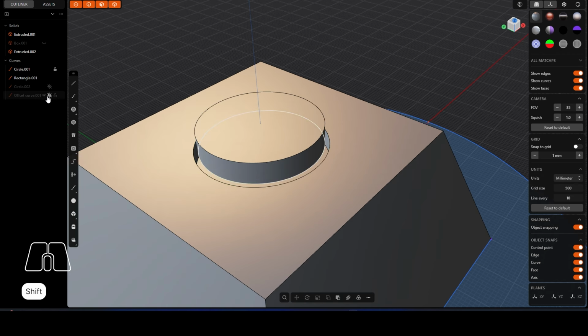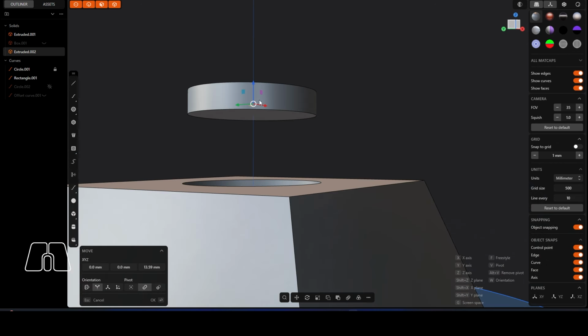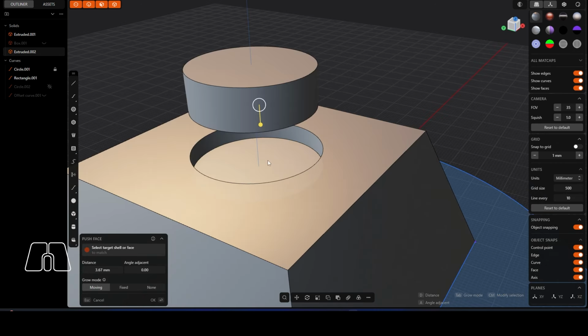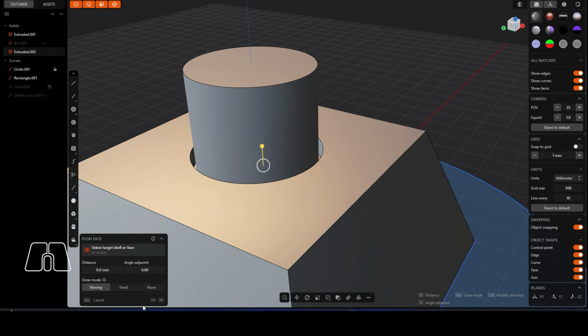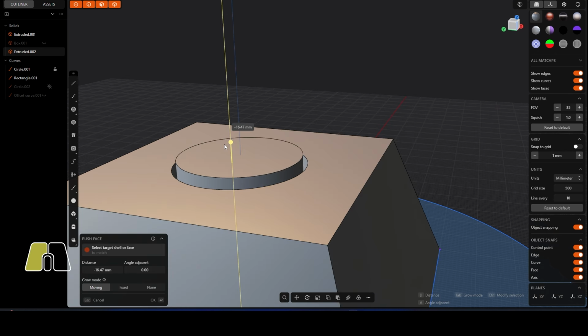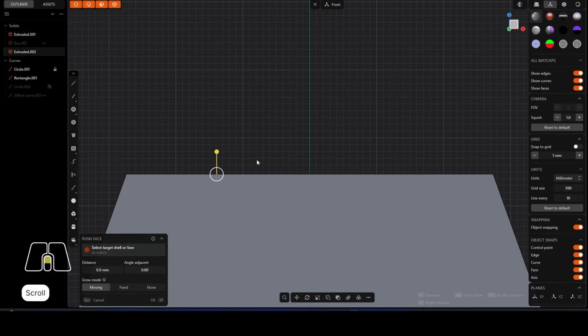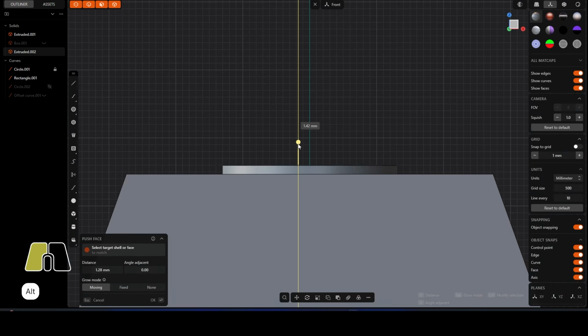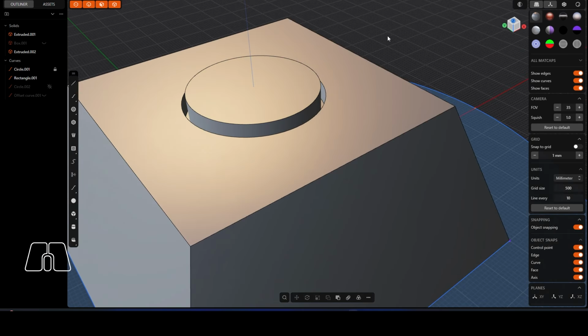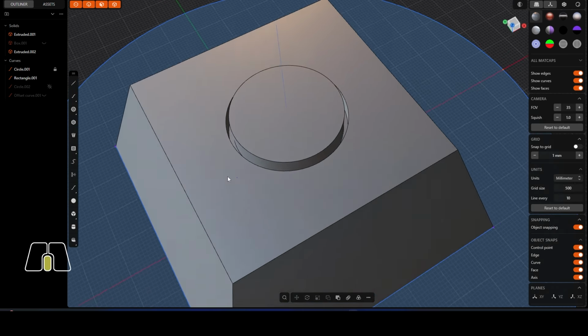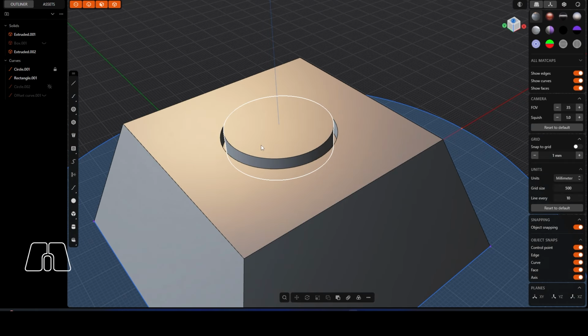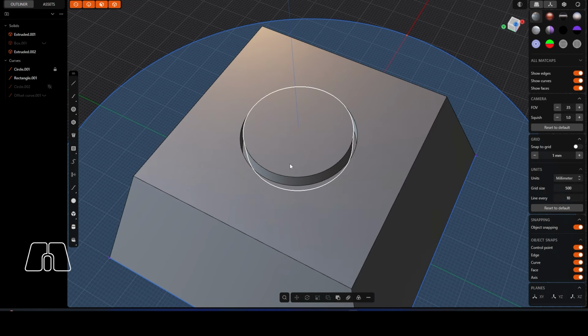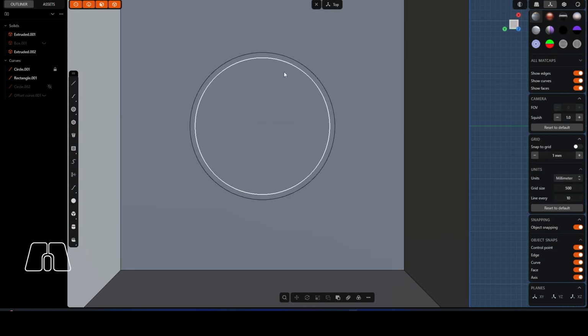We can go ahead and hide each of these circles. And then what we can do is I'll just move this up. I'll grab this piece here, move it down and snap it onto the base there. And then we've got an option to just move this into a position, so we can get it something like that. And then what I'll do is just come back and I'll set that, I think I had it to 2, and there we go. We've got a really nice base there. It's got a little offset there, so if you've got your different parts that you want, you can slot this in. You can make locks for it as well, so perhaps maybe you want this a little bit more intricate where it locks in, so you can put locks in here.